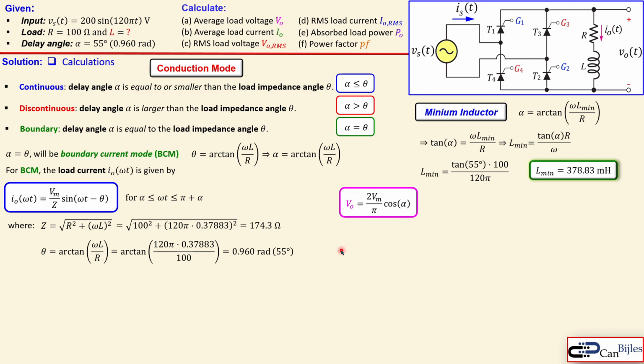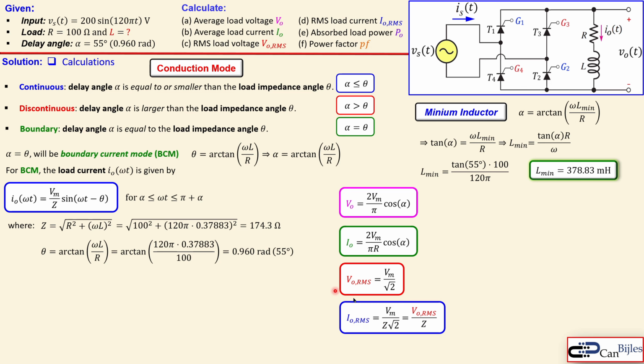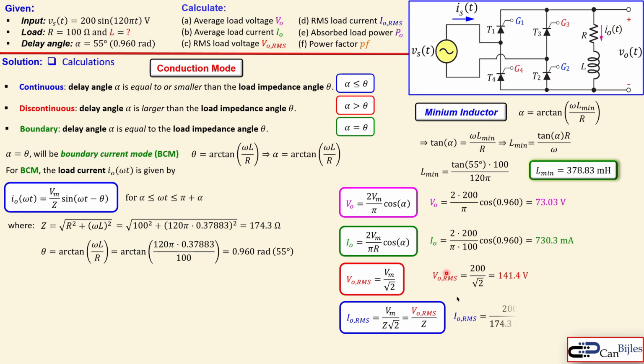For the average load voltage, the formula stays the same, and also for the average load current, and the RMS load voltage will be exactly the same. The only change is the RMS load current here, which is much simpler than before. It uses this divided by the impedance, sort of Ohm's law, and then you have everything from A up to D. So let's calculate that again. These are the values we have here, and this is now the RMS load current, which is 811.2 milliamps.